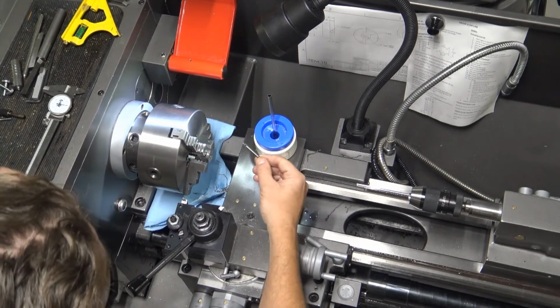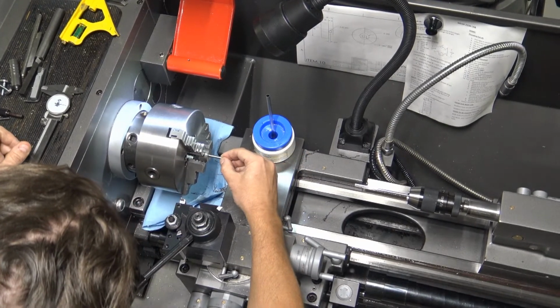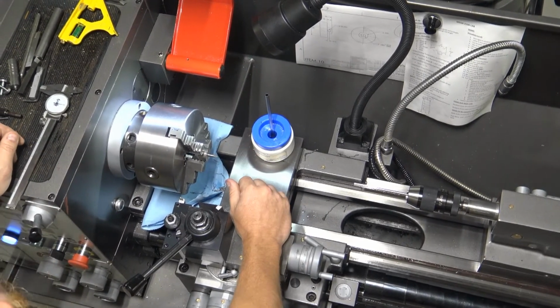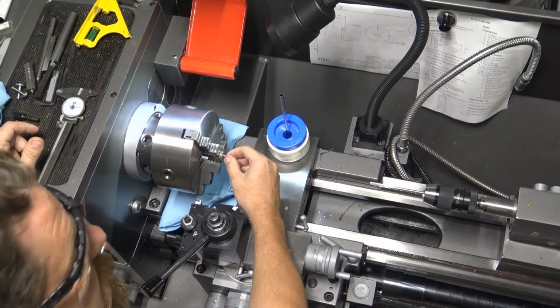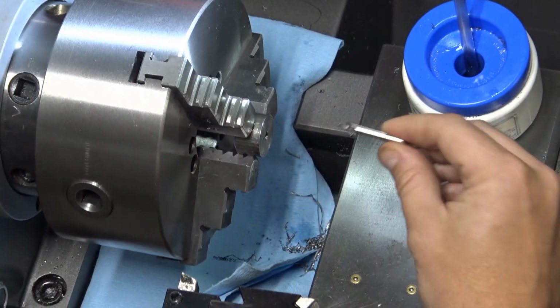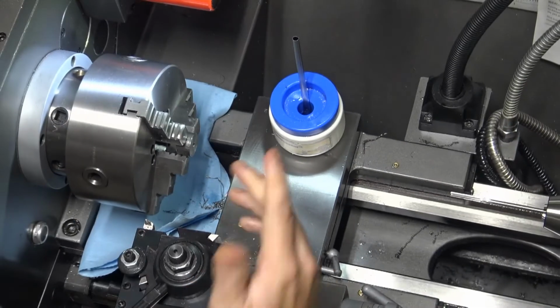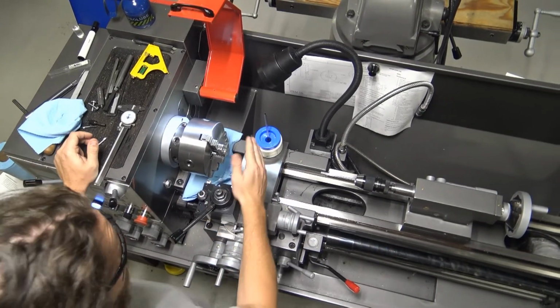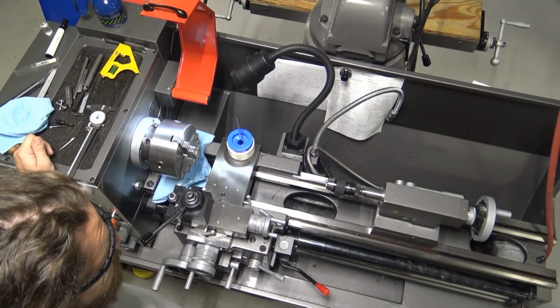So as a quick check, if that number 2 center drill goes in, we used the right reamer. If it doesn't go in, you used the wrong size reamer. All right, it should just barely slip in there, nice and tight. All right, so we used the correct reamer. We've got everything done on this face that we want to do.